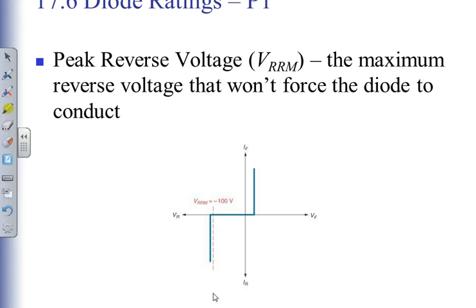semiconductor to conduct. So the air in this room, if I had 1,000,000 volts on that wall and minus 1,000,000 on that wall, the air in this room would in fact conduct. And there'd be large bolts of current going through the room, and they'd be very dramatic. And if we were standing in the way, they would be going through us. Okay, so if I have enough reverse voltage on anything, I'm going to break it. Diodes are just little things. Minus 100 volts is going to be all it's going to take.